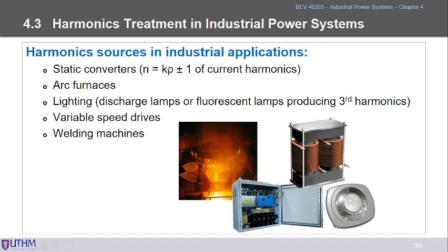That means the 5th harmonic and the 7th harmonic are the lowest ones. So it is impossible to have third order harmonics and so on in this case. If we keep increasing K, say K equal to 2, then 2 times 6, because we have 6 pulse, is 12. 12 plus minus 1 means the next harmonic contents will be 11 and 13.